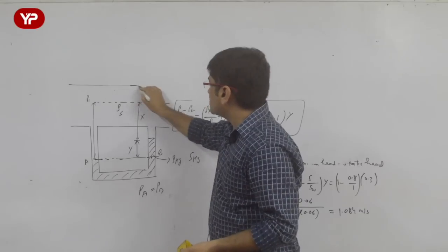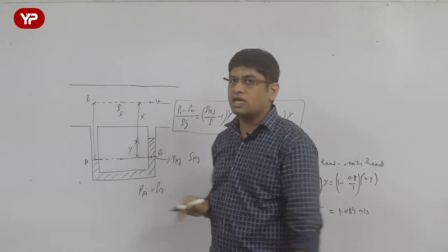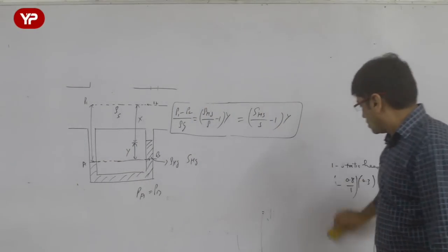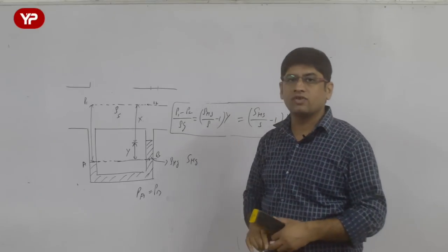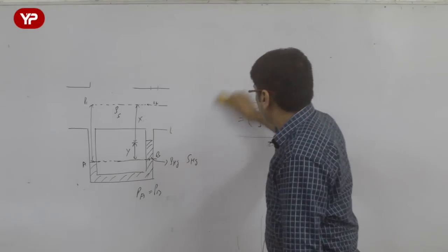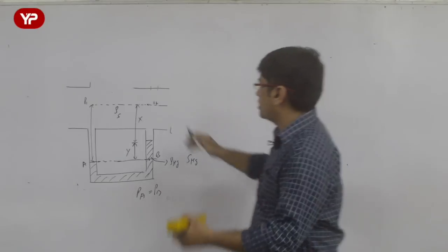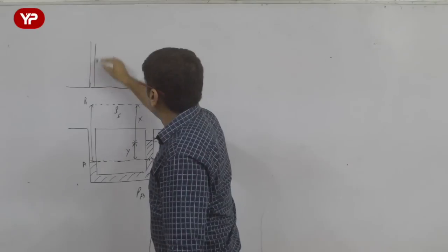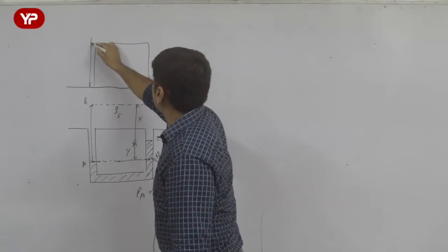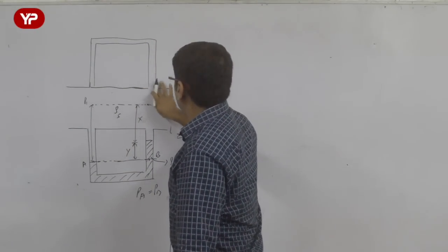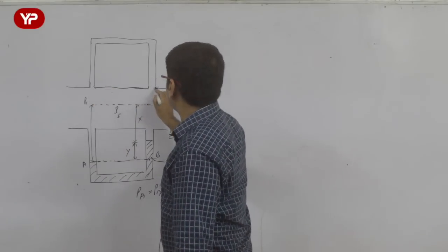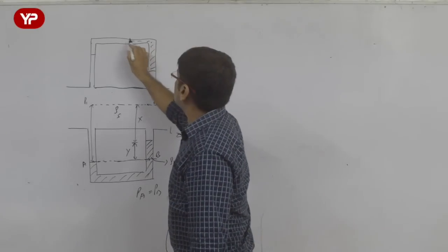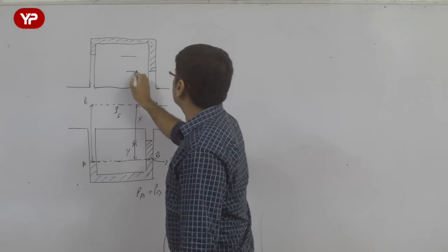Now suppose the pressure difference between the 1 and 2 states is very less. Pressure difference is not much. Then instead of going for a U-tube manometer, we go for an inverted U-tube manometer. Let me clean it up again and make an inverted U-tube here. Let us say I have an inverted U-tube manometer between the two sections. Okay, this becomes an inverted U-tube manometer. Now the fluid which is used in the inverted U-tube, let us say this limb difference is Z.